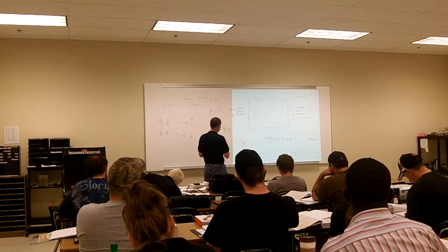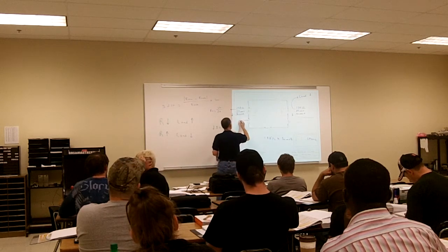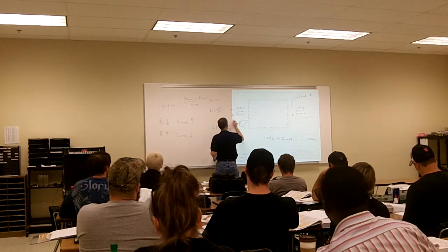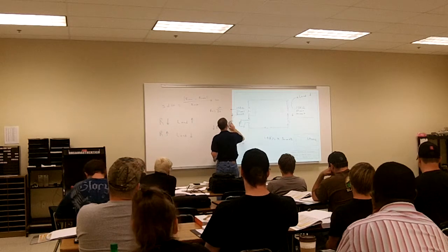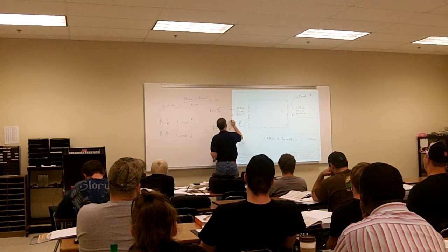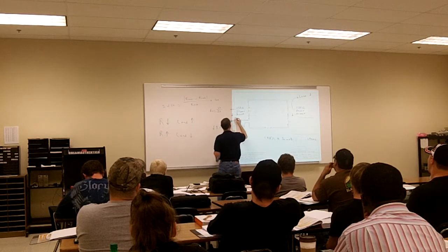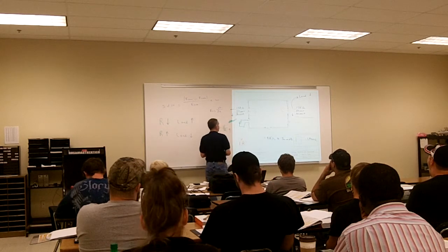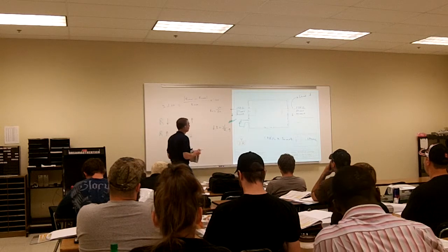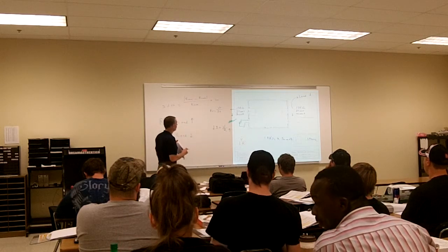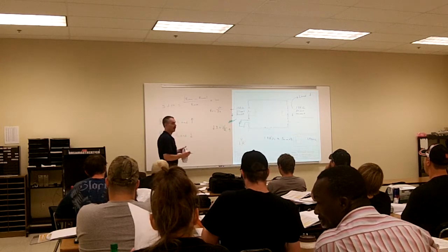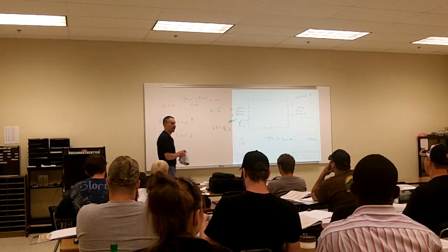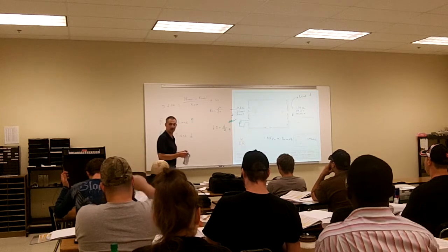All right, if I measure my fuse and I measure 24 volts or 54 volts, is my fuse good or bad? Okay, how many people say good? Raise your hand. How many say bad? Yeah, it should be bad.